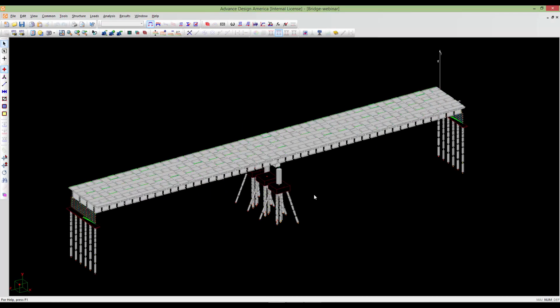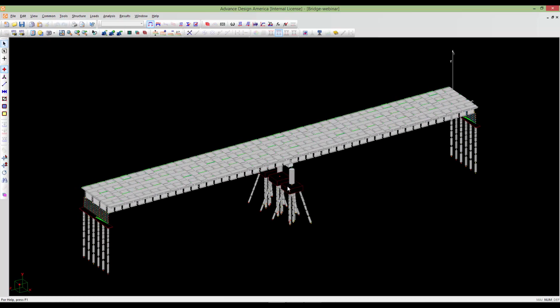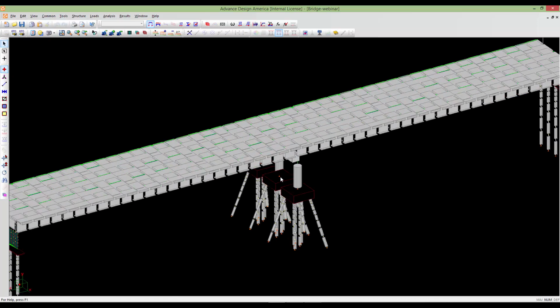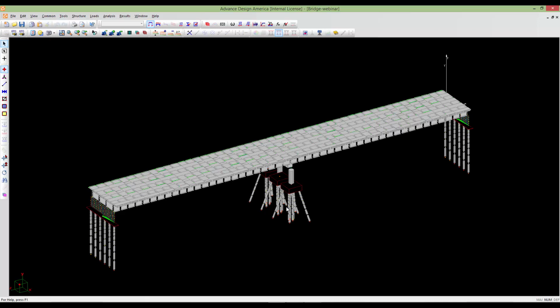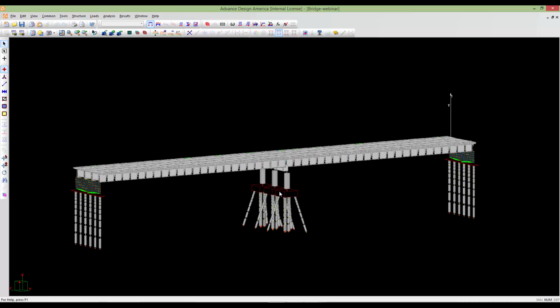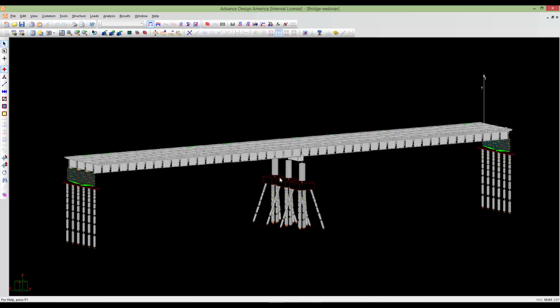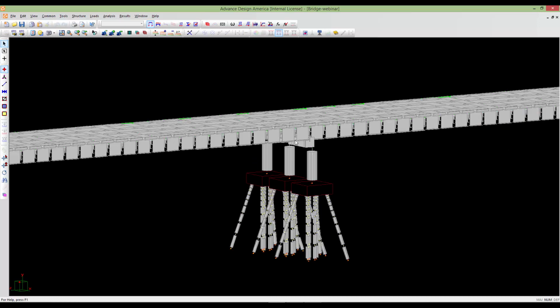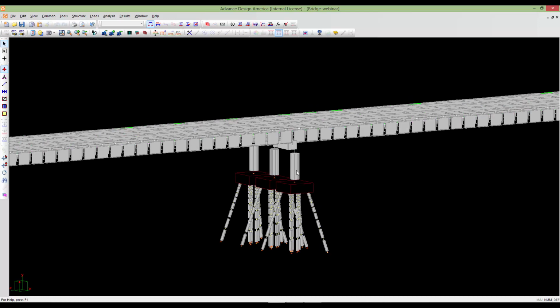The next stage is to define your seismic levels for this structure to calculate the spectral forces. So to define each seismic level, we can just select a node from that specific level and assign it a seismic level.